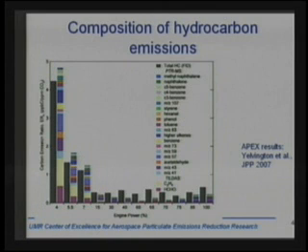But the points I want to make here are that in Apex 1, we did a very fine stepping of the power conditions, not just the handful that we looked at in JET's Apex 2. So we have very detailed power conditions here, and we're comparing the detailed hydrocarbon speciation that we're measuring this way with the flame ionization detection measurement that's required for certification. You can see that overall the same things are happening: we have a lot of hydrocarbons at idle where the combustion inefficiency is lower, and very low, approaching detection limits, at powers above 15% power or thereabouts. So we have general agreement, and we can discuss in detail the difference between the FID and the measurements shown here.